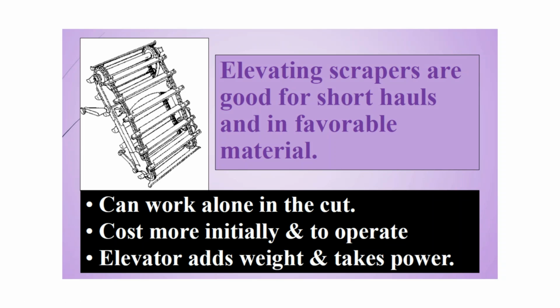The elevating scrapers or self-loading scrapers can work alone, but they cost more to initially purchase and they cost more to operate, and it takes power away because the elevator takes power from the blade.